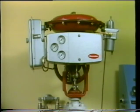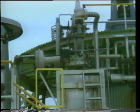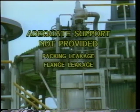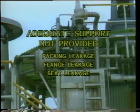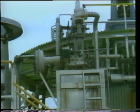The attitude of the control valve also needs to be determined. Every effort should be made to keep the stem oriented vertically. If vertical orientation is not possible, actuator support such as this may be required. If adequate support is not provided, stem misalignment can occur. This can cause packing leakage, flange leakage, or seat leakage. Additionally, hysteresis may also increase. Similar problems are introduced if piping to the valve is misaligned, creating stress on the valve.